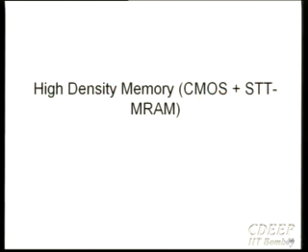Finally, I just thought this is important. Any kind of high performance device that you really think of has to have a lot of memory. My friends in the architecture community tell me that in today's high performance processors, you certainly have a lot more transistors available every technology generation, and where do these transistors go? It turns out mostly to the memories. The memory size of a high performance processor today, compared to the rest of the circuit, takes about 70 to 80% of the die area. So you put more into the on-chip memories, so that as long as you don't have to go off-chip, you get better performance. That's the reason why we need to think in terms of very high density memories.